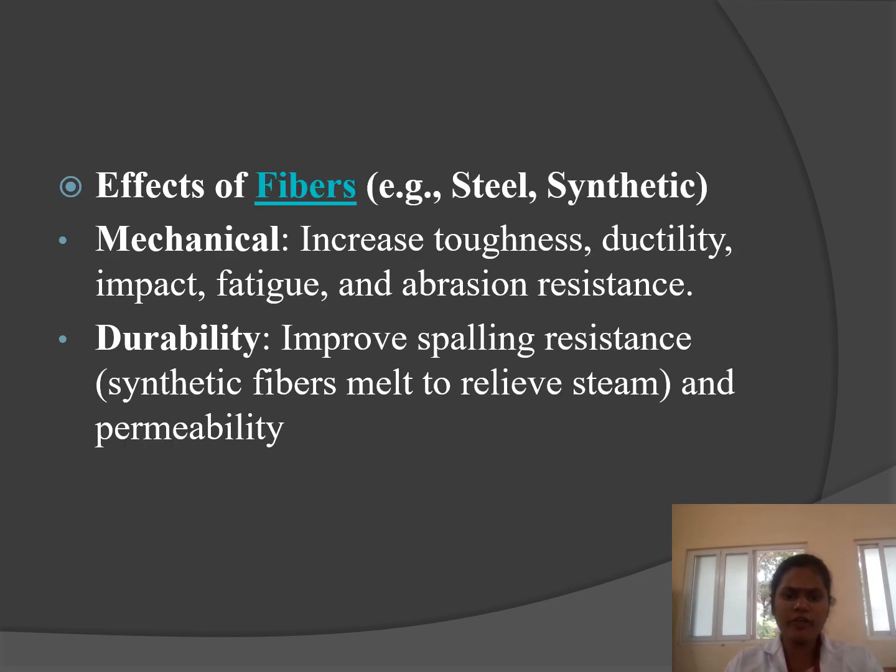Next is the effect of fibers, for example steel and synthetic. Mechanically, they increase toughness, ductility, impact, fatigue and abrasion resistance. For durability, they improve spalling resistance and permeability.